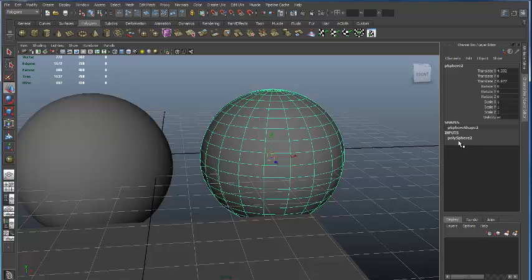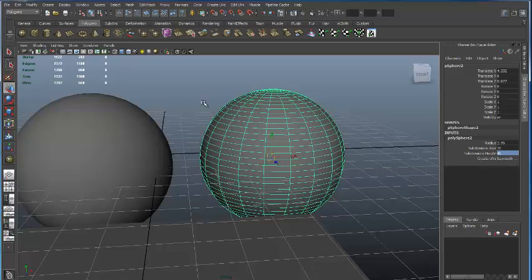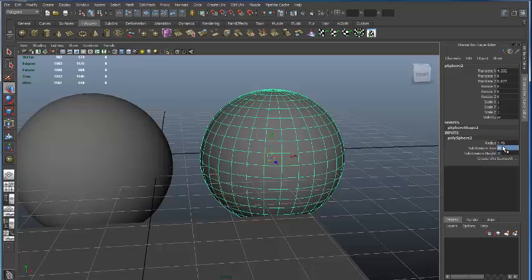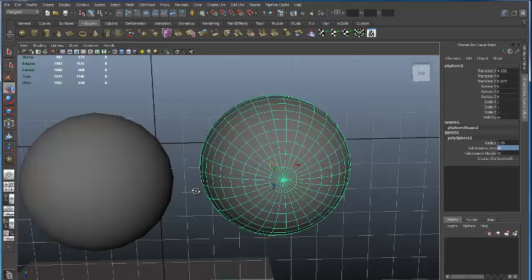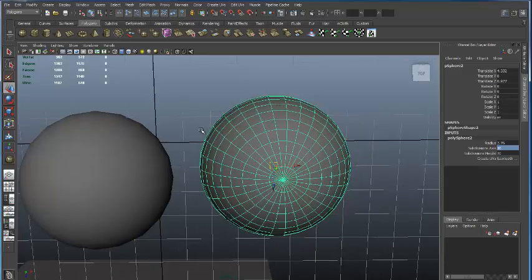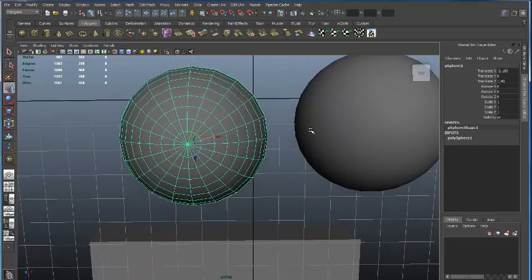So I'm going to go into the input selection here for this particular object. I'm going to come down and under height. If I adjust the height, look at what happens. It's just putting more subdivisions in the height, and that's not really the area that I want to affect. What I want to affect is a subdivision of the axis. I'm going to raise that to 30. Okay, and if I look at it from a top view, you can see how I have much less linear angles as compared to that original topology here.